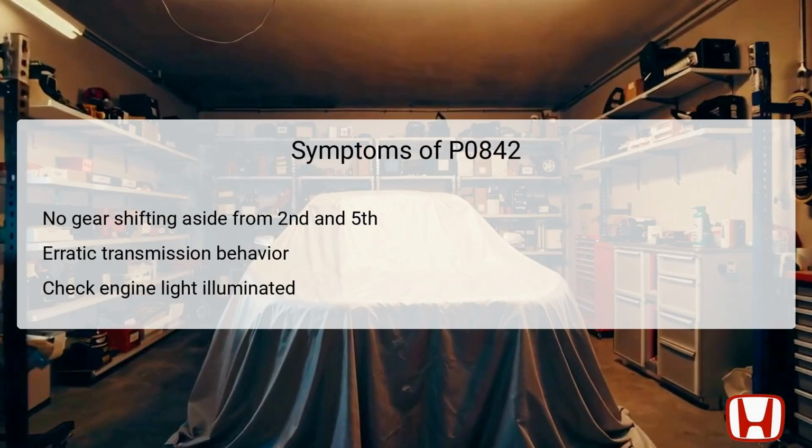When the DTC P0842 is present, the driver of the Honda Pilot may notice several symptoms. The most prominent symptom is the limitation on gear selection, as the transmission may only be able to shift into second or fifth gear due to the fail-safe feature activated by the PCM.